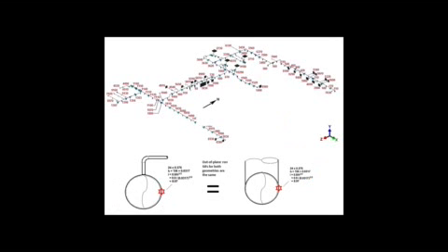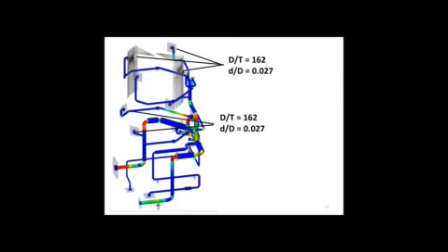Let's take another look at a typical piping system, okay? Big piping system, the first thing that comes to my mind is the high SIF problem. If you run this model on Caesar without making any modifications, you have no stress problems, everything is fine, stresses are all very, very low. If you look at the criticality count, if the stresses are less than 20%, you can divide by numbers. So if you've got a very low criticality count, you'd never worry about it. As soon as you start having higher stresses, or if you've got tight portions of the piping system, or small D over T ratios where the SIFs are way off, now you want to start zooming in and taking a look at it locally.